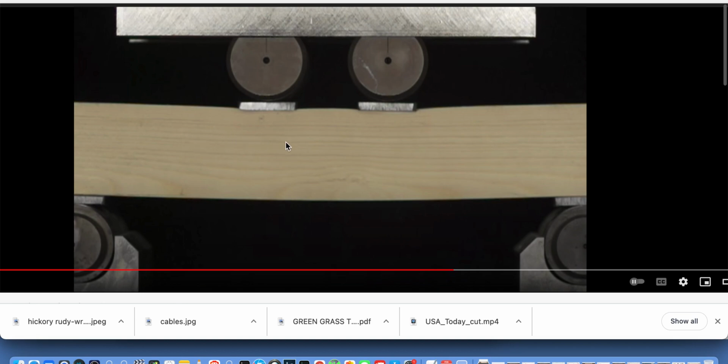I'm also saying think of these as stirrups, and now when you see the grain structure like this, think of these as rebar stirrups, as rebar, if you will. So they're stirrups because they're in the tree, and they're cut that way. But if it's loading this way, then look at these as rebar. If you turn it the other way and load it, look at it now as the stirrups, and you've dissected it, and you can imagine it would fracture easily and separate along all these planes of rebar